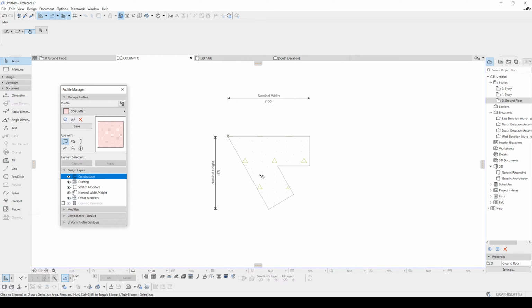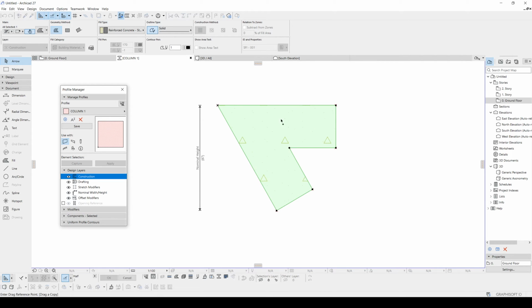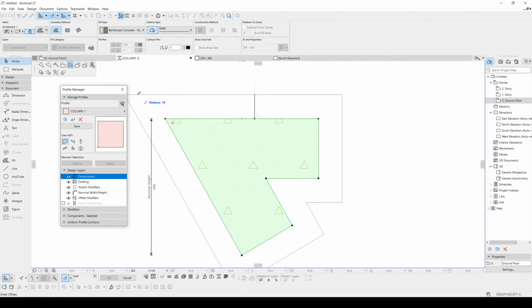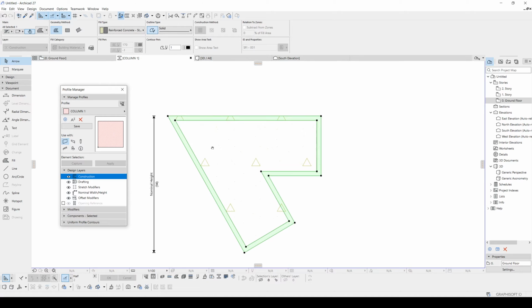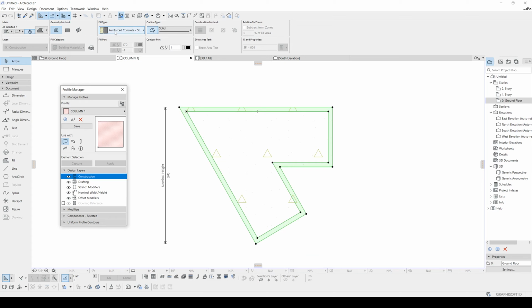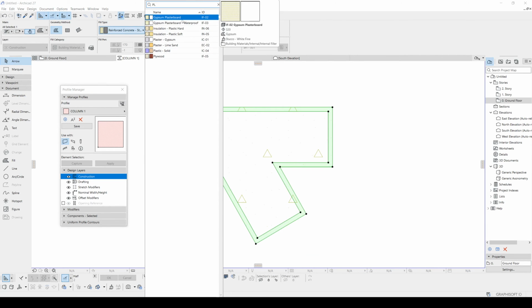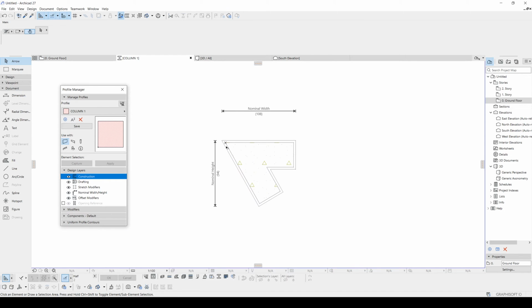And after that we will create additional hotspots. Under the document, click hotspot, click your corners one by one. Once this is done, you will duplicate this column on its own position, and then we will click the edge, then offset, hit 3 and click the edge, click this minus, subtract from polygon, hit space, and you will see inside column, select your new surface. It's going to be veneer, plaster, and fill type will be plaster or gypsum. There we go. Now our column is ready.